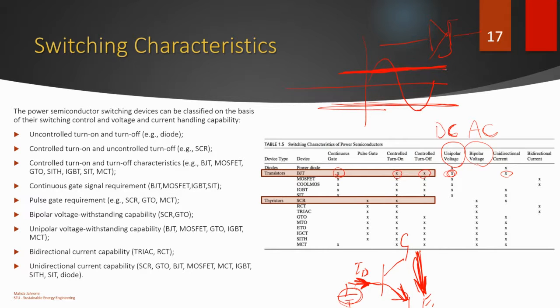It only cuts it when you have a reverse voltage. If I apply a sinusoidal voltage, and let's say the peak is 10 and my Zener voltage is 5, it only cuts the voltage on the negative side, where you have the reverse polarity. So the voltage becomes like that. You get it flat here. You don't get the rest of it.